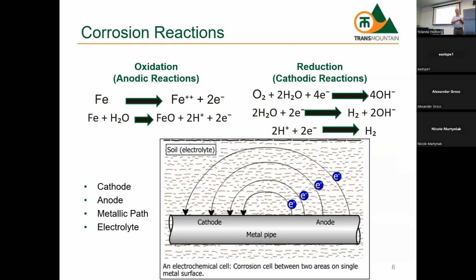Okay. Which metals are amphoteric? Does anyone know what amphoteric means? Yeah, it's an acid base. Aluminum. Yep. Yeah, so aluminum, when we protect aluminum, we want to actually minimize this reaction. Okay? We can't let the potential of the aluminum get too electronegative because the pH actually goes into the amphoteric range where it corrodes at a high pH. So that you also have to combat with cathodic protection.